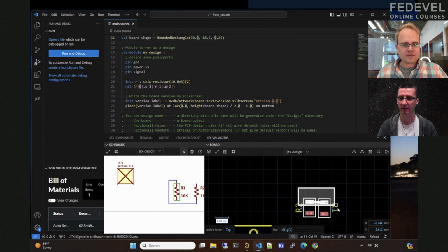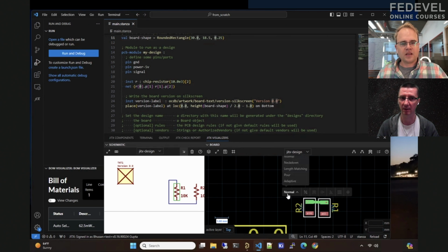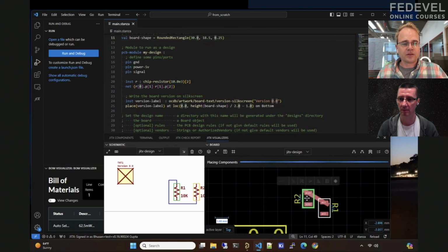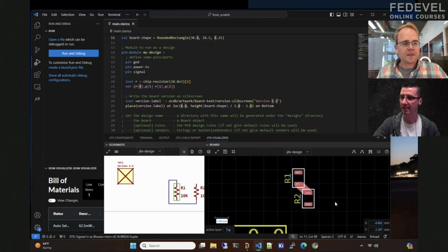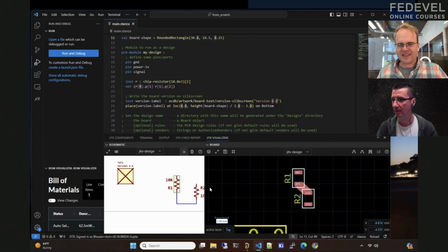So when you have some power pins connected together, then basically the auto router will create power planes automatically. Exactly. Yeah, and this plane is just a trace. So here I set it to be adaptive, and it'll take that shape. And yeah, you get to move your layout around, which is nice. And your traces, they all update. I see schematic has been updated. Yes, schematic is updated. There we go.